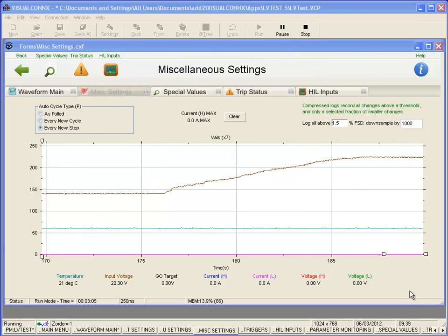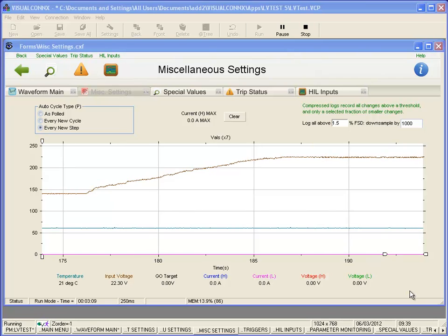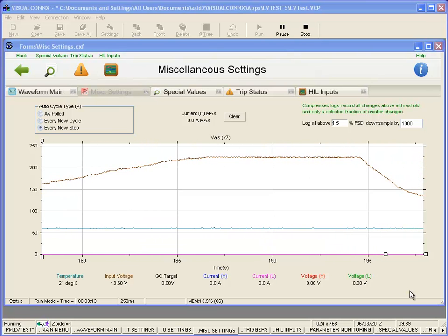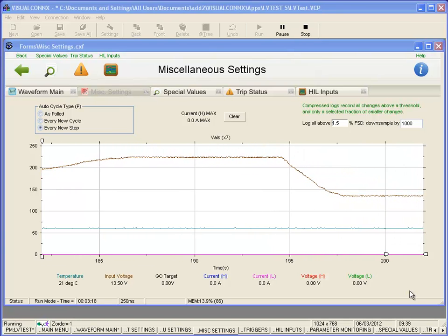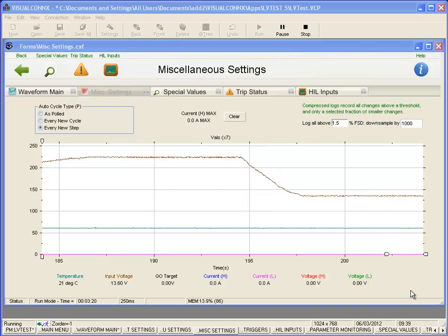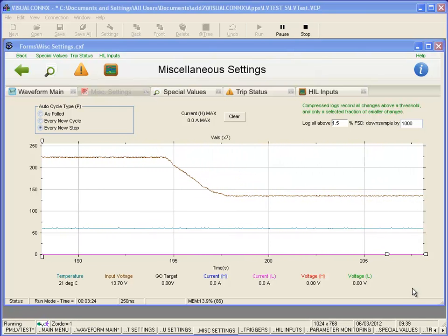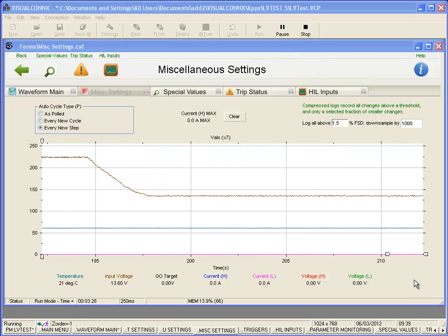While the voltage is too high, you will hear the unit continually giving warnings. As we reduce the voltage down to normal range, the unit continues to indicate a slow warning out of the audible indicator, and also the front trip LED will flash together with the noise.